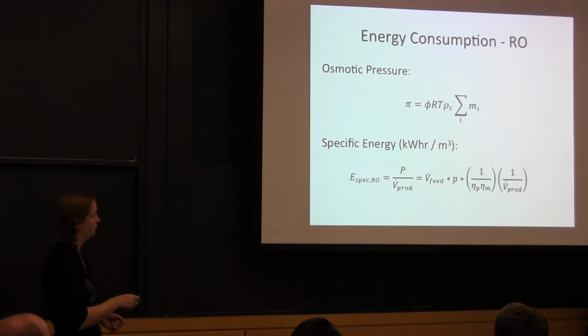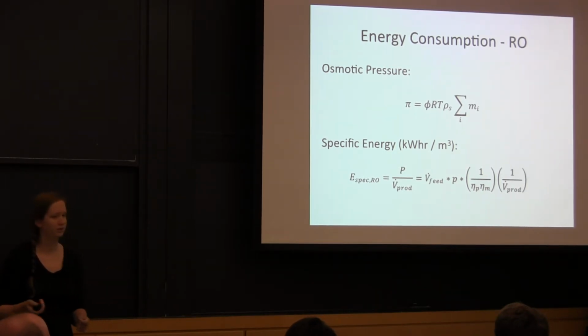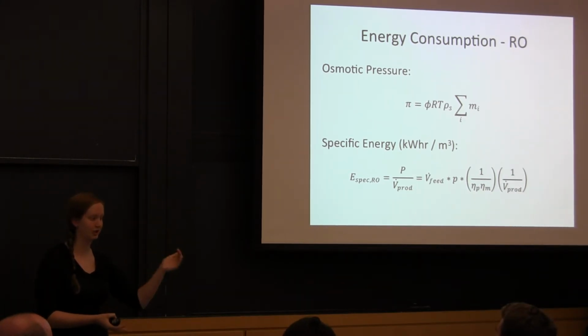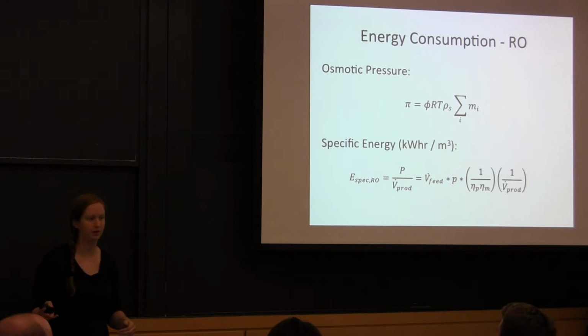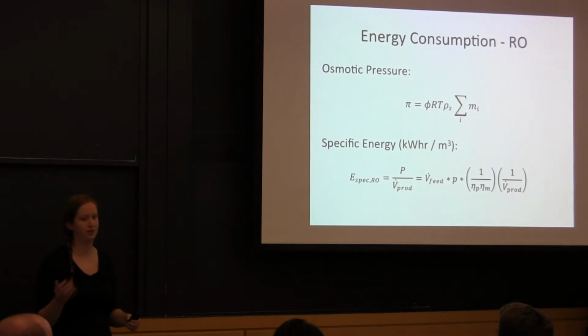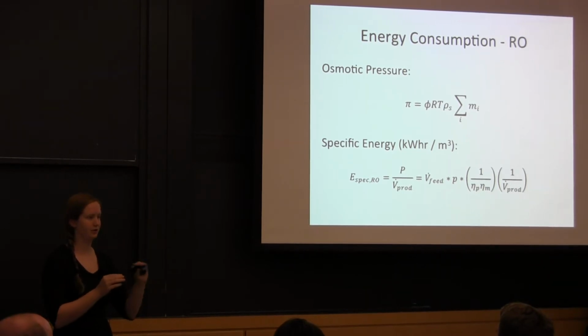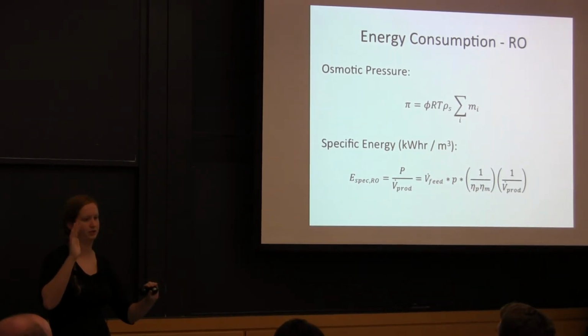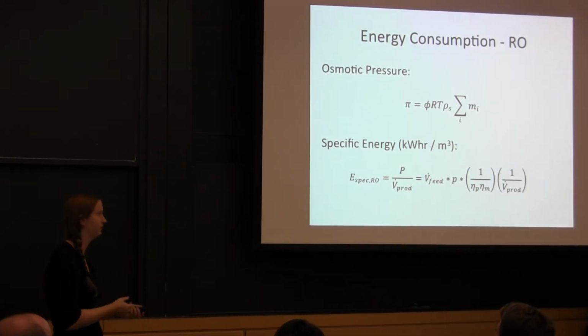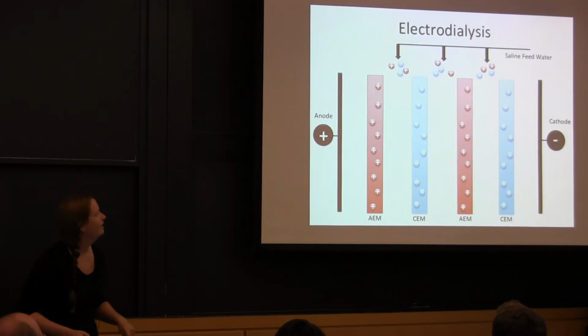One thing to consider, though, is that for these low salinity streams, too high in salinity to drink but still low in comparison to seawater, the applied pressure is actually even greater than the osmotic pressure, because the osmotic pressure is fairly low in these cases. You're applying a pressure that has more to do with the flow rate through the system than the osmotic pressure. Anyway, that's just a side note in case you're wondering where the numbers come from later.